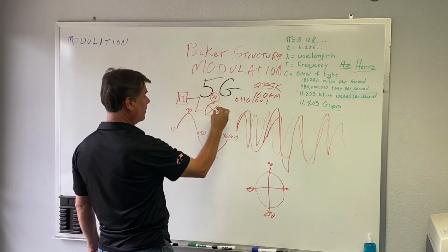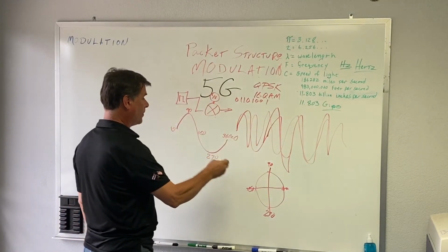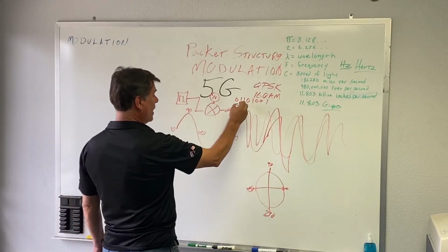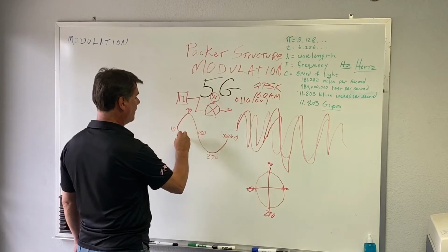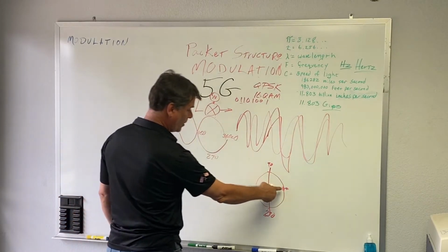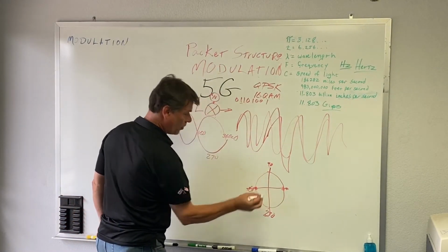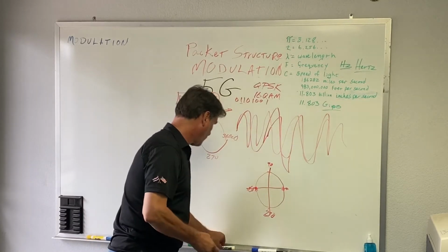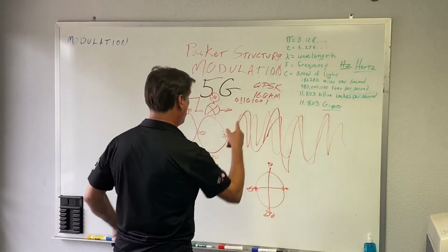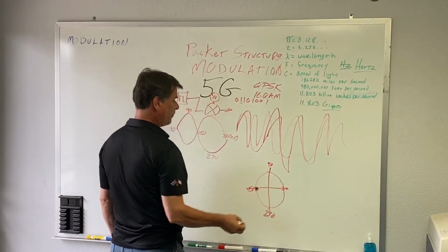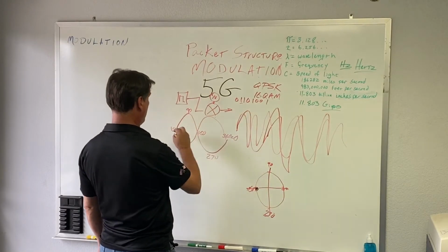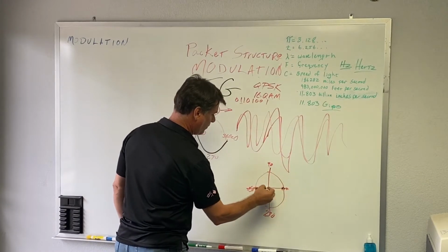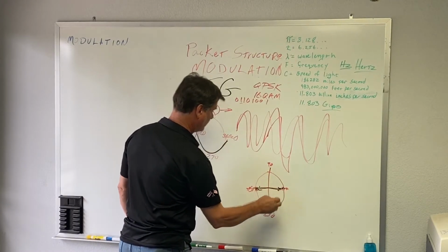This is the simple oscillator. This is the modulated output. So we've got a 0 in there. We're in phase. The next time slice, we put a 1 in there. That flips the phase 180 degrees, which on here is drawn like that. So that's where our phase is now. Next, we've got another 1, so we stay at 180. Next, we've got a 0, which means we flip back to that first phase, right there. So we went from that phase angle to that phase angle.